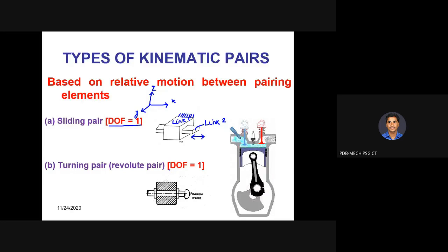It is also indicated that the degrees of freedom is 1. Okay, so it is your link 1, namely the bush. Link 1. This shaft is your link 2. Link 2. This collar is here in order to arrest the axial movement of the shaft. This shaft will be stopped from moving like this. Okay, in the collar. So now if I fix link 1,